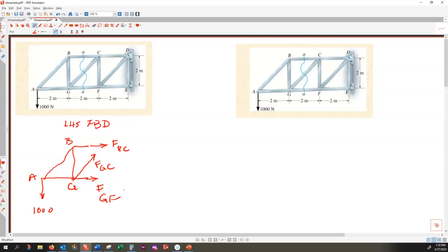Well done. That is free body number 1, 2, and this is 3, right? And 3 unknowns. Is this free body diagram solvable? How many conditions do we have for this one? Yes, Nguyen is right. This is solvable because the forces are not colliding at one single point.